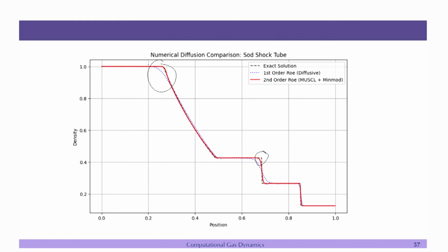But because you are dealing with these complicated flows, we need special treatment, and we also need to increase the order, and we need to be very careful, because if you increase the order, as we have seen earlier in the case of Lax-Wendroff, you will start seeing wiggles, right.